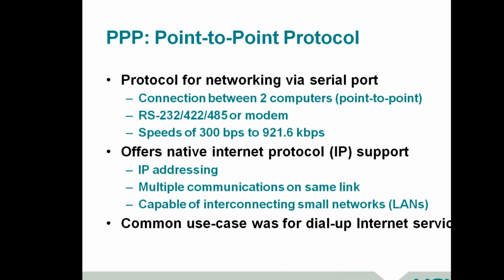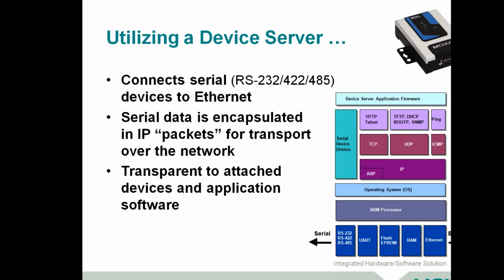And for light duty applications, this works out really nicely. In essence, it gives you an IP connection at both ends of the link. That means you can run multiple things over the same communications path, multiple protocols. So for example, you might be monitoring Modbus to one device and maybe using proprietary or specific technology to go to a device, or maybe use a web interface on port 80 for that, all at the same time over that connection.